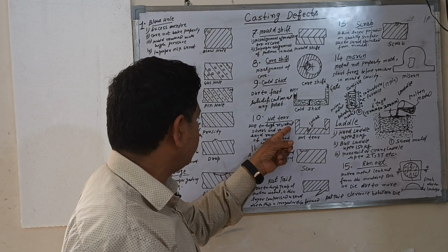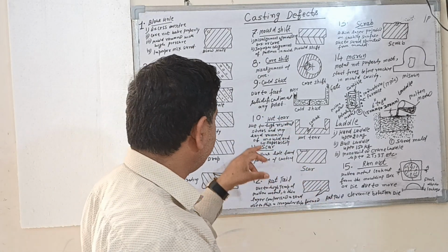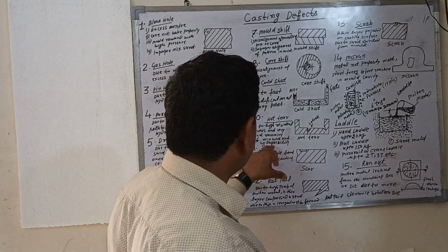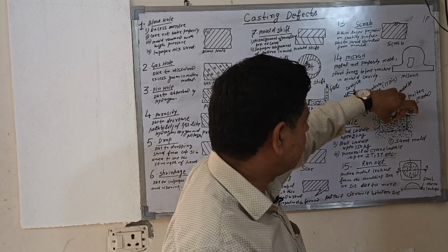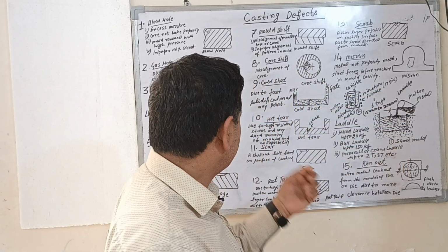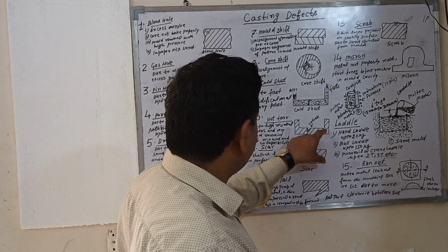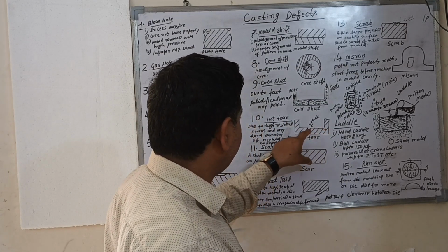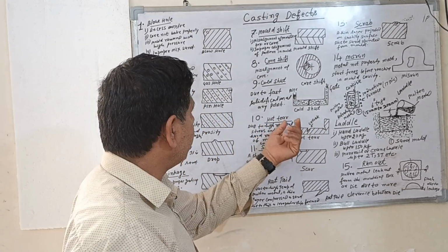due to the high radial stresses and very high ramming of the mold sand. Collapsibility means the mold binding, the sand binding, is split out. So due to the collapsibility, the hot tearing occurs, and this type of joint breaks at any point in this form. This process is called a hot tearing defect.